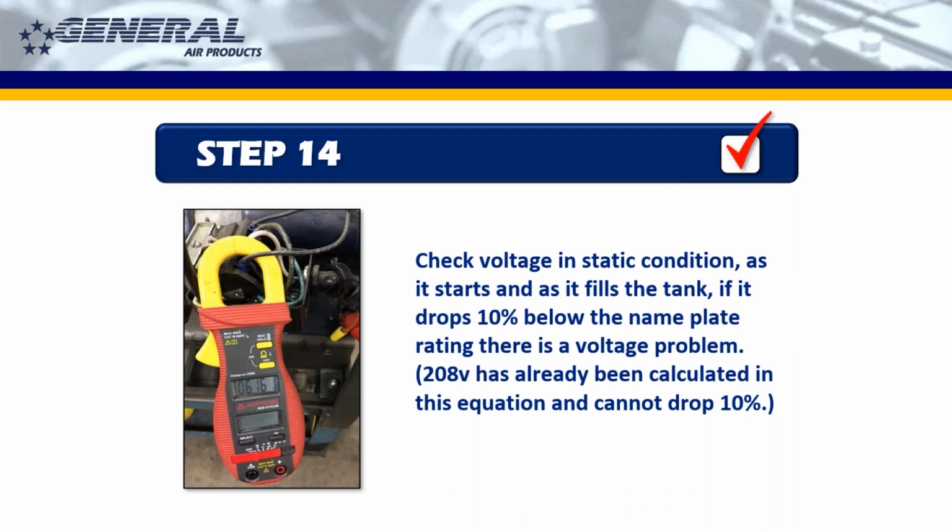It started out at the panel at 115 volts. By the time it gets to the unit, because of volt drop, you're going to lose a ton of that, and it's going to be down to 60, 70 volts that the unit's getting. If it's extreme, you're going to see the unit really running, and it's going to sound really beat up.